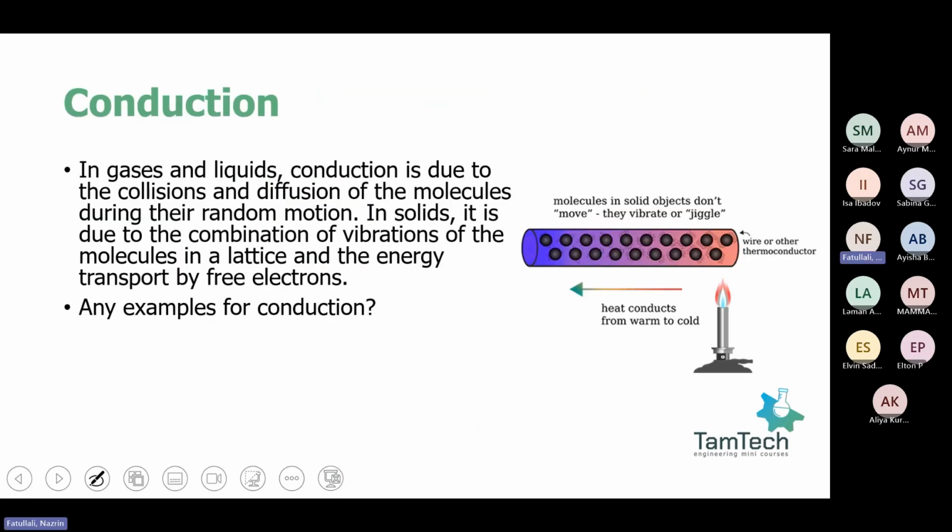And now I'm moving to the modes of heat transfer. The first one is conduction. I'm pretty sure that you have heard about it. Think of it like heat moving through a material, but the material itself doesn't move, as you know. In solids, for example, the atoms are locked in a lattice, they can't go anywhere, but they vibrate and pass energy from one to another. This is applicable for solids, but in gases and liquids it's slightly different, because here molecules collide and diffuse and pass energy from one to another.